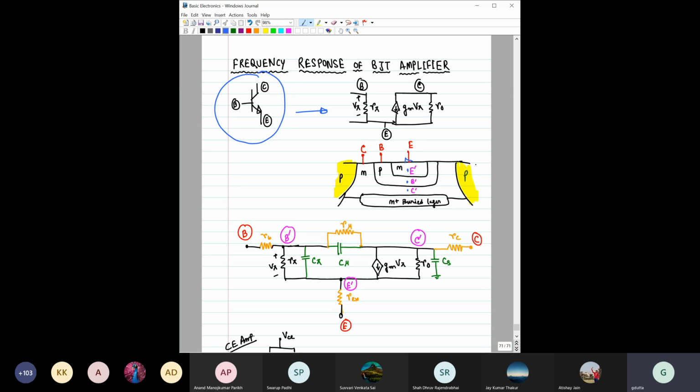When you connect any metal with some semiconductor, there will be a potential drop. That means that will offer a resistance between this outer lead and this inner node, right? The same thing will also happen for the base, and the same for the collector. And things become even worse where the doping concentration is less. So for the collector, the resistance offered from here till this point would be quite significant, right? Compared to that from this emitter to the E dash terminal.